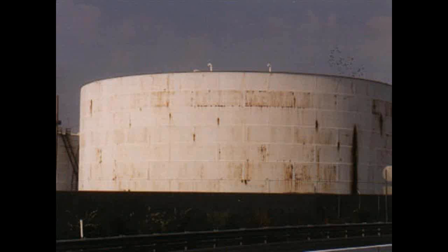This particular photo, I use it as an example of where to test. If I were a specifier or an inspector and I wanted to find any contaminated surfaces, I would look at areas where the coating had failed. I would look down here where there's areas of corrosion. I wouldn't bother testing right here. That's good, sound, intact coating. If there were any salts behind it, it would have failed. So just the fact that it's sound, intact coating tells me that the salt levels there aren't of a concern.